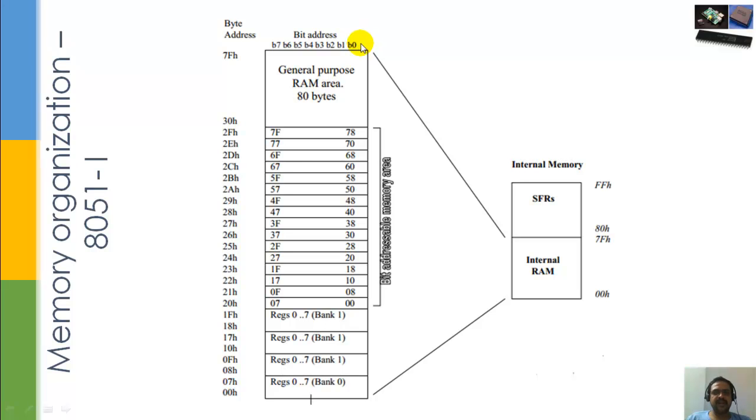Whenever you programmed in Keil, you saw a set of general purpose registers available for your data manipulation, right? R0 to R7, that is 8 registers, right? But the element of surprise here is there are totally 4 banks. Bank 0, Bank 1, Bank 2, Bank 3. 4 banks with each containing 8 registers. So ultimately, if you look at 8051, for your data manipulation, you have totally 32 8-bit general purpose registers. But only 8 are available per bank.